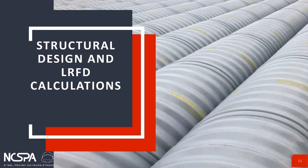During our second session, we covered the structural design methodologies used to develop fill height tables for each standard diameter, gauge, and profile of corrugated steel pipe and pipe arch using both the AISI methodology and using AASHTO load resistance factor design calculations.